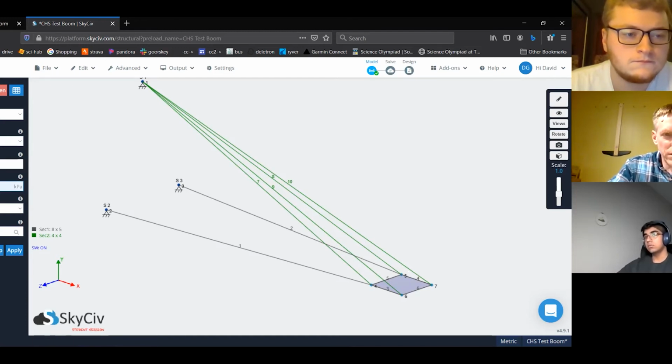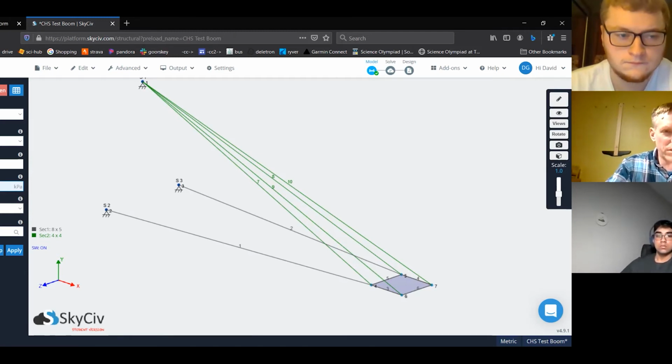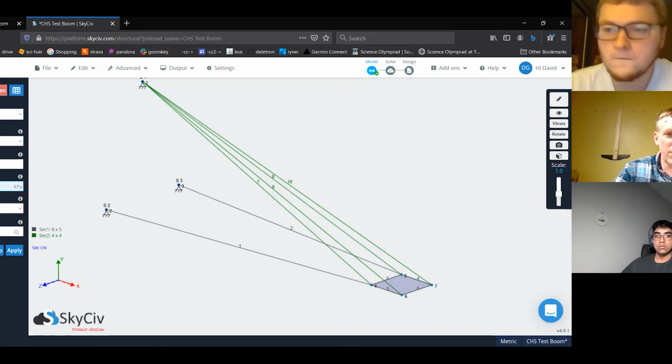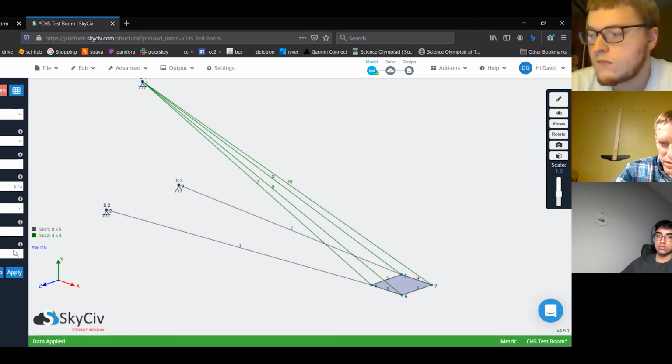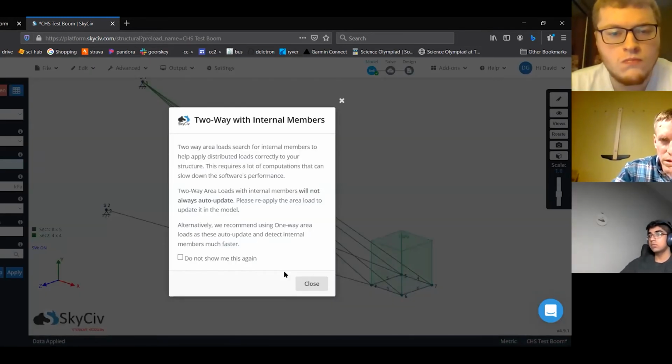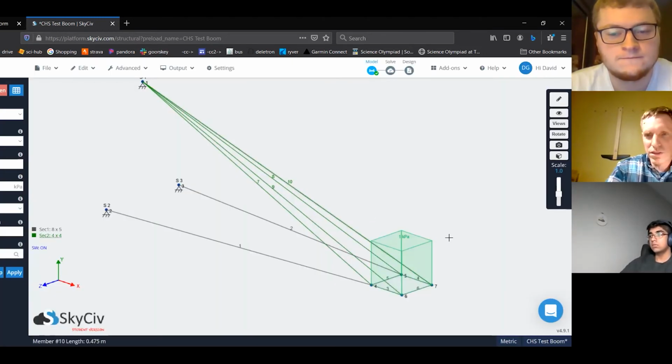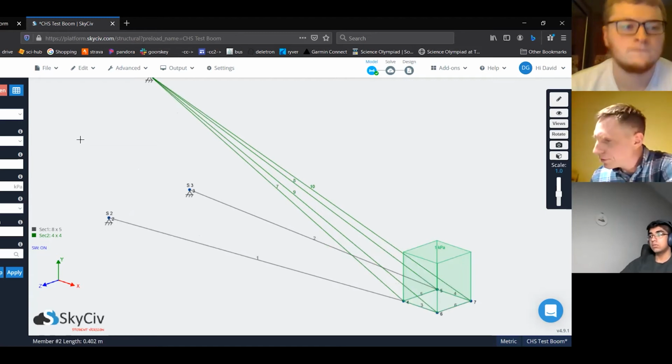And then the pressure magnitude, you can just set it to be whatever. Actually, I think it has to be minus to go in the negative direction. It'll change that eventually as it's testing it, right? You just need to give it some initial pressure, which you don't need to worry about. Just give it a minus value, and make sure it's on the y-axis. And then you apply. Then you don't need to worry about that. And so that essentially puts a loading block on it. Let's see if there's something else I'm missing.